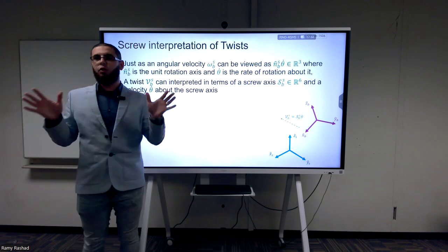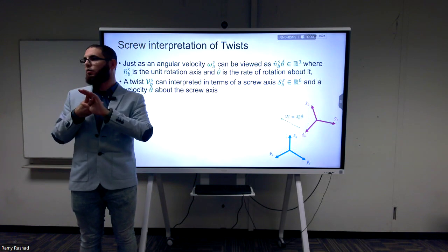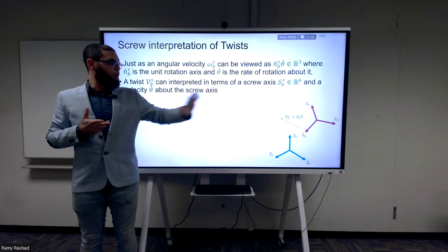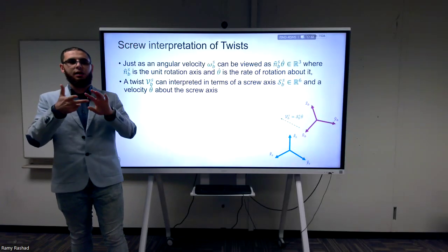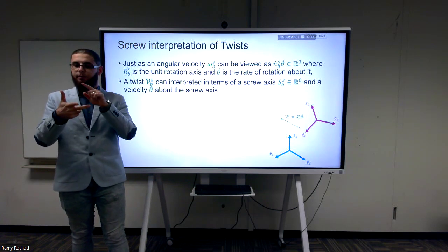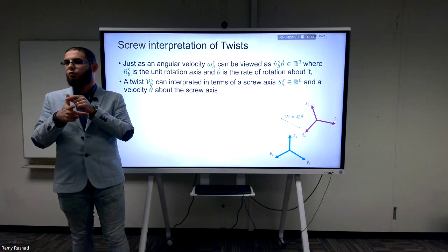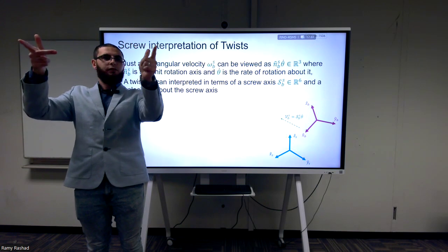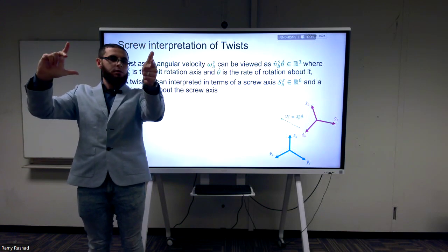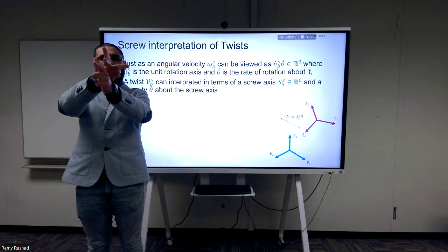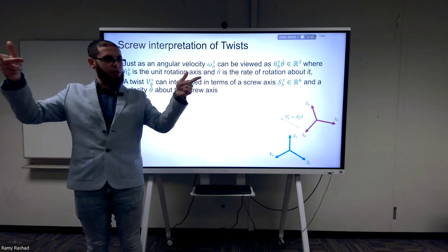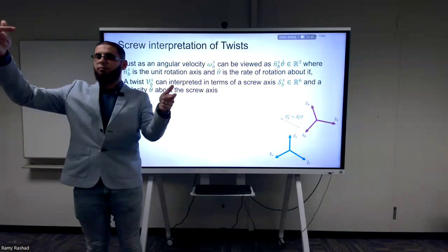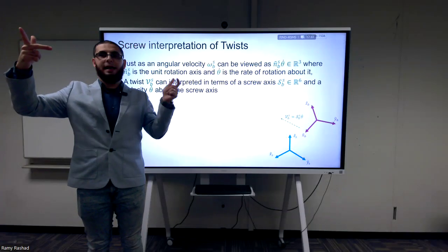When we say we have rigid body motion, we're talking about two things, right? We're talking about rotation and translation. If we have a screw axis, it can have 3 conditions. It can have either a pure rotation, which means that I have this frame, and this one is rotating with respect to that frame. So this is pure rotation. But you see now I'm not at the same point anymore. Even though I'm displaced, so there are two frames displaced from each other, the motion itself is simply pure rotation. The other case is pure translation.